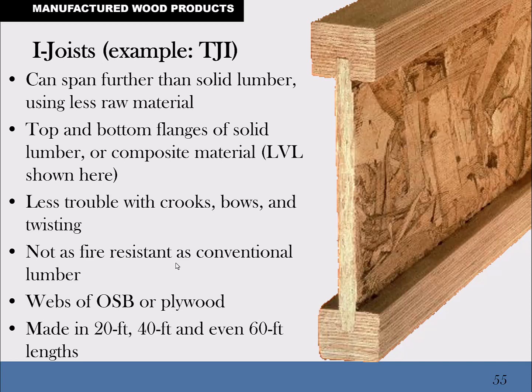So that's the kryptonite, and you need to remember that's the testable point that can show up here that I want you to know, is that these wood I-joists, they're not very fire resistant. They are the worst, really, of all the wood products.